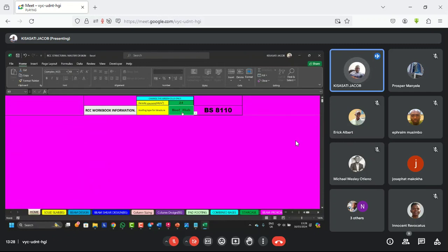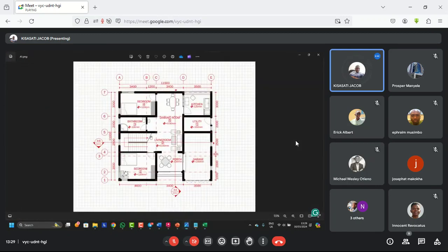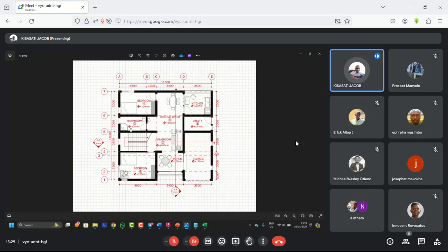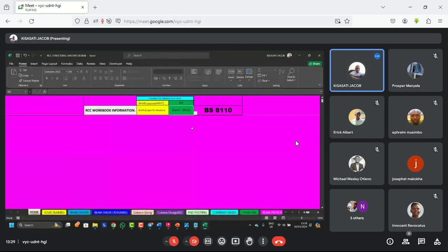We have a roof with access and a roof without access. We are going to discuss all those in BS 6399 Part 1. So for this building, for this plan, we will just assume it's a 4-story building with a roof slab, and this roof slab will have water tanks to supply water to these people, because now they must have access to water. So we are going to allow it to have a roof slab. Then of course we can select a structure with a roof, but this one we are going to use the roof slab, and we'll discuss some more things at this point.